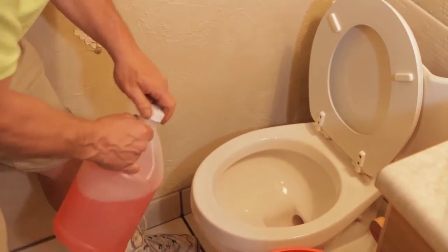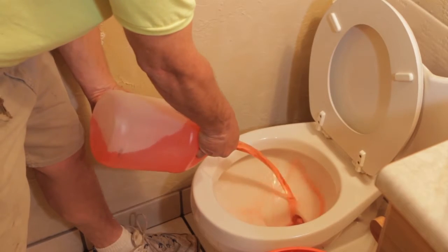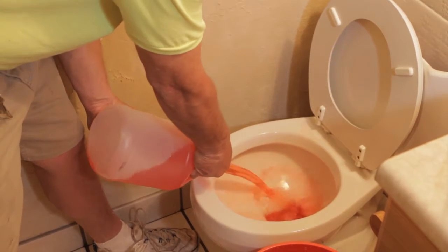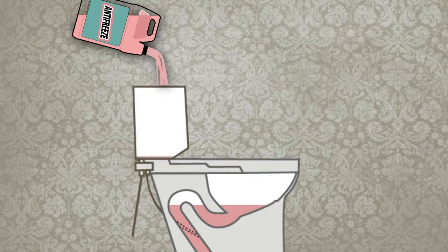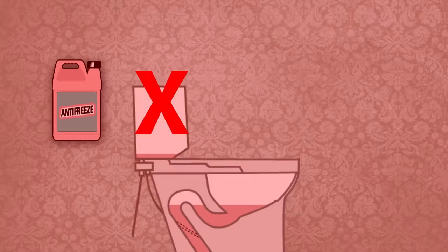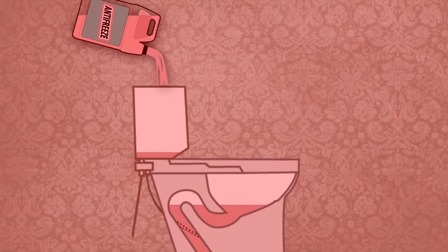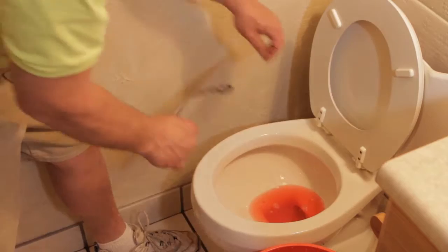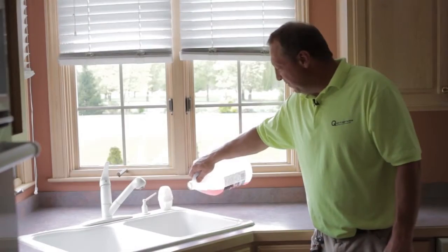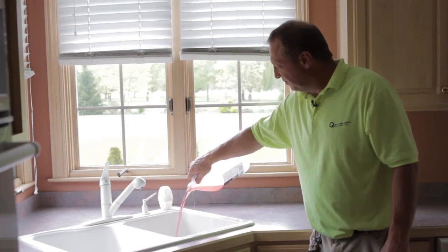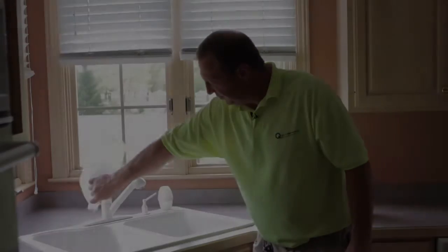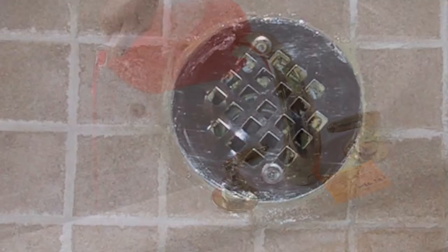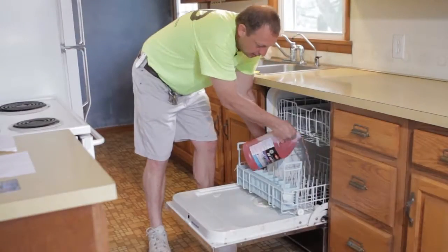After all water is removed, pour non-toxic antifreeze into all toilet bowls above the siphon line and also into the toilet tanks above the rubber flapper. Next, winterization wraps are placed on each winterized toilet. Additionally, antifreeze needs to be poured down all drains, including but not limited to sinks, bathtubs, showers, and dishwashers.